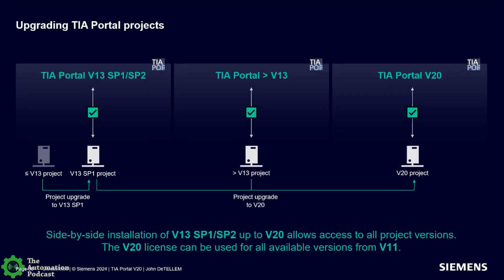Of course, TIA Portal version 20 will open a version 20 project, and it has the capability of upgrading any project back to v13. They made a mandate at v13, fundamentally 2013, I think, 2014, to support that format all the way through into the future. So v20 will open those projects, any one of the versions. It can be installed side by side with those versions, 15, 16, 17. So I can do operations and engineering in both worlds, v20, v17.